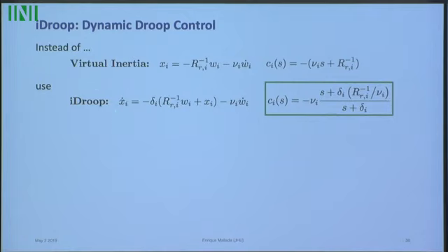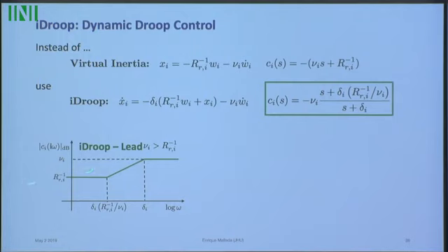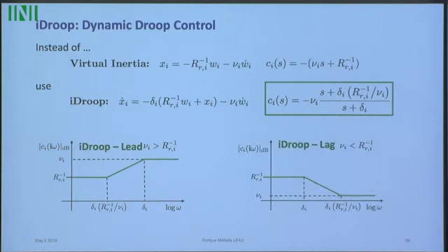So essentially, you integrate this term and you add what we call a stable pole, a filter, you can call it. And this additional degree of freedom is going to be actually very helpful. In particular, you can get different gains. You avoid this large amplification that gives you the noise. But also, you can have different gains for the steady state, which is what Droop had to commit in a step change, and the one that you use for your dynamic performance. And you can work it as a lead or a lag. That's our term that we use in control.